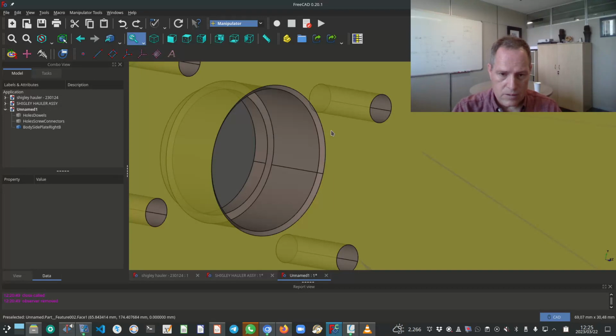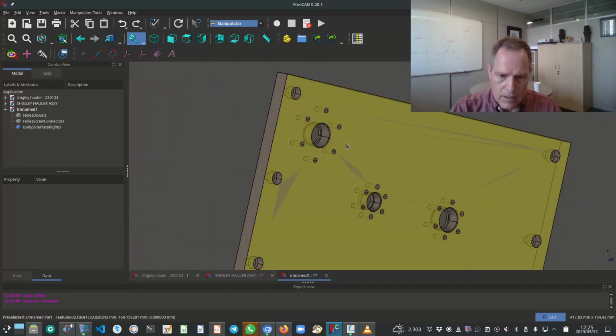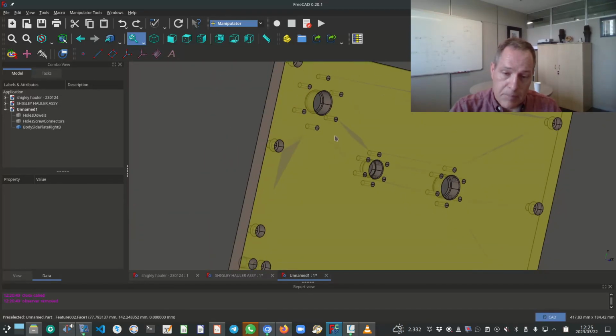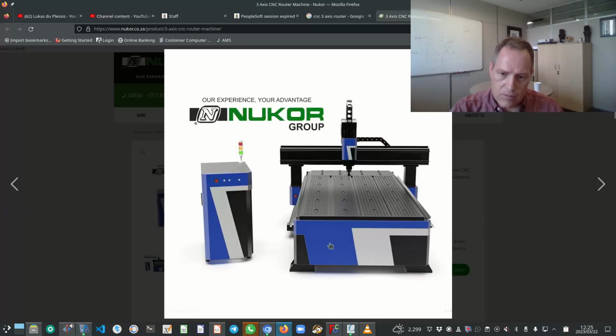You cannot specify a depth from one side and from the other side. For this application, all the depths need to be specified from one side, which is the side that will lie flat on this face. That's our datum from which the depths will be measured. So I hope that is clear.